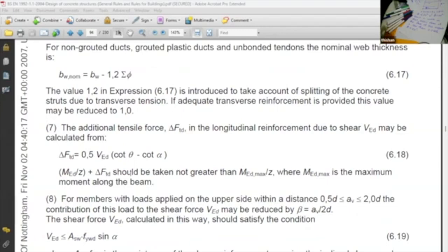So generally, when you are curtailing, in the early days we used to have the hanger bars as the smaller reinforcement, and additional reinforcement used to come in the middle. But that is not the practice that we follow now. Now we run the larger bars as hanger bars, and then we provide smaller bars as additional reinforcement.